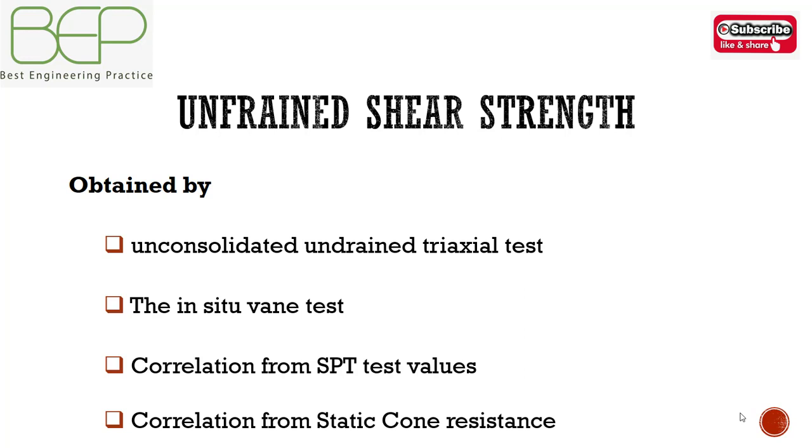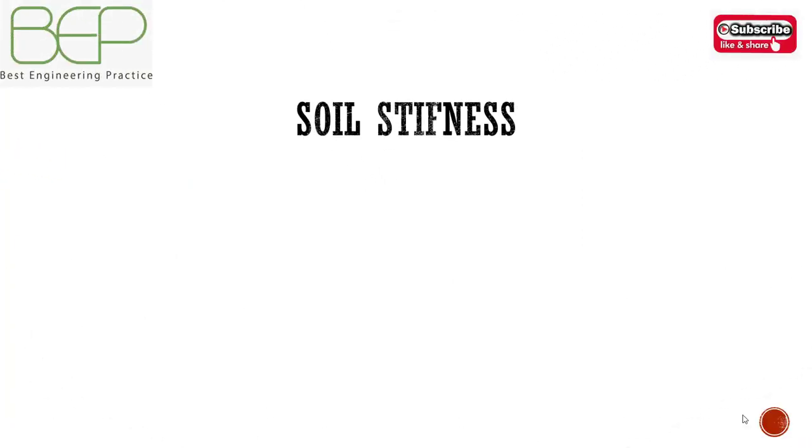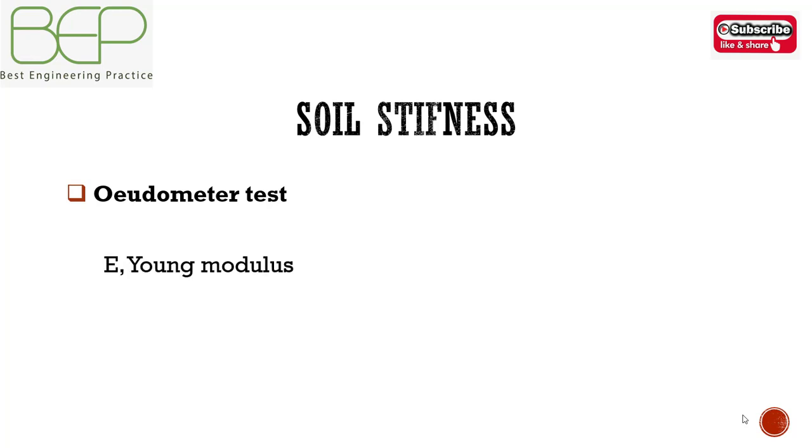In the absence of test data and for small structures, only an approximate value of undrained shear strength can be obtained from records. For small walls, where a design can be over-conservative without unacceptable financial penalty, it is acceptable to use the result of oedometer testing to determine a value of Young's modulus of clay, for example, to determine the settlement of a gravity wall. Strictly and ignoring bedding, the constrained effective modulus E'c is obtained from the coefficient of compressibility determined from an oedometer test.